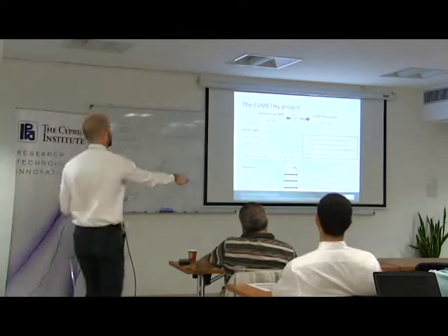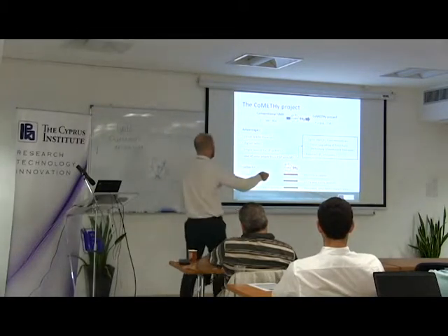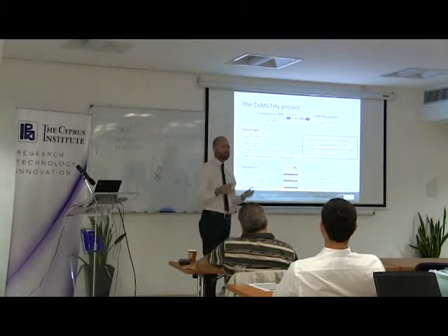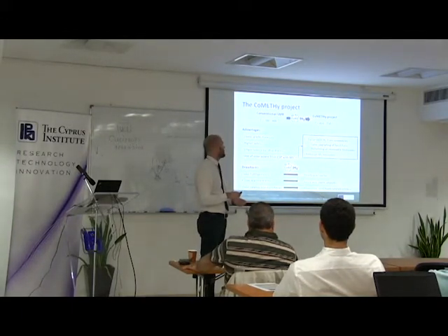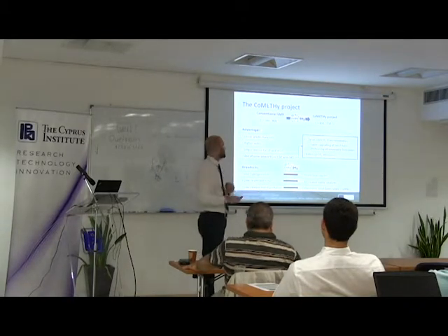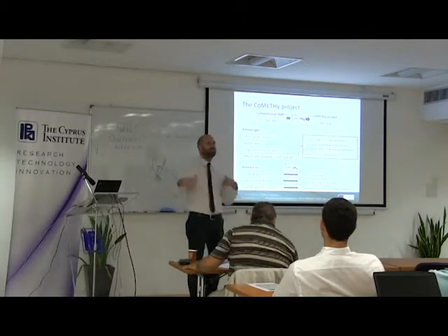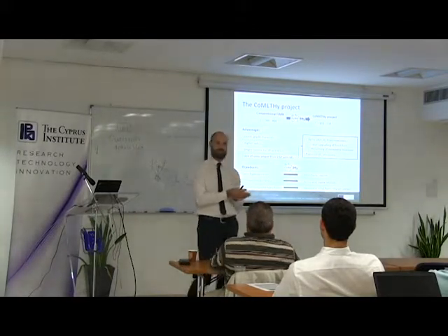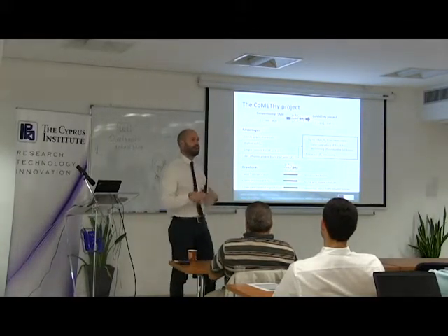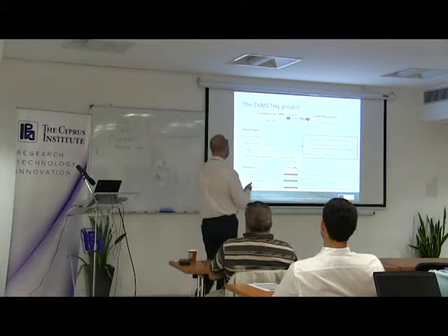And in a temperature range where we can use the consolidated heat storage approach in the CSP industry today, which means double tank molten salt. This is perfect. 550 Celsius degrees, 450, you can use solar heat and you can benefit from the commercial solution for storage. So you can ensure a smooth and continuous operation of the plant.